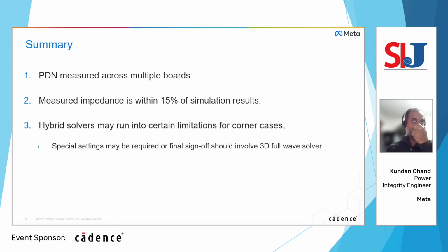So overall, just a summary, we did the PDN measurement across multiple boards for both bare board capacitance, bare board inductance, as well as on the populated board, the decap populated board. Overall, we were able to correlate within 15% of the simulation results. And we tried different solvers, including hybrid solver as well as 3D solvers from different tool vendors.